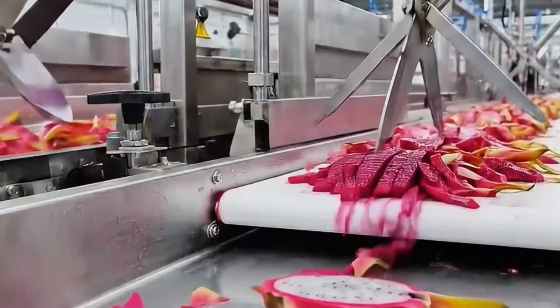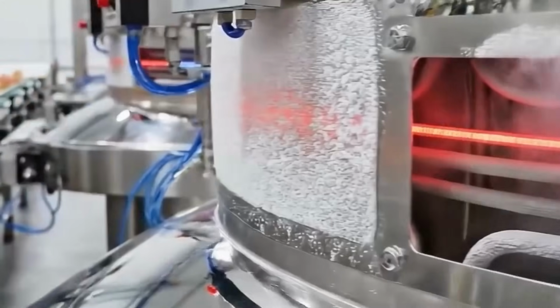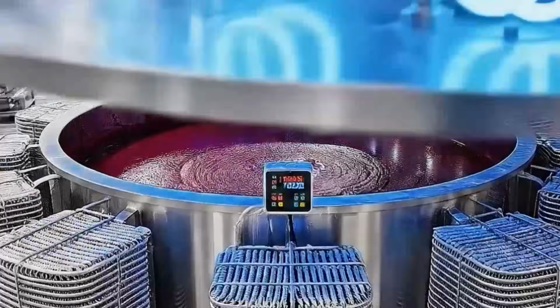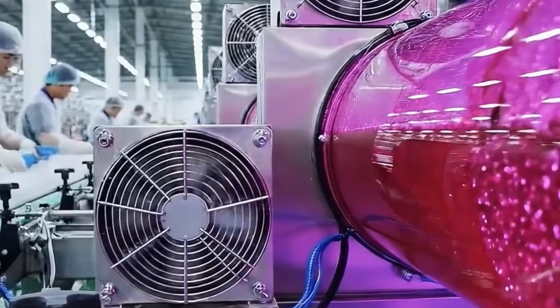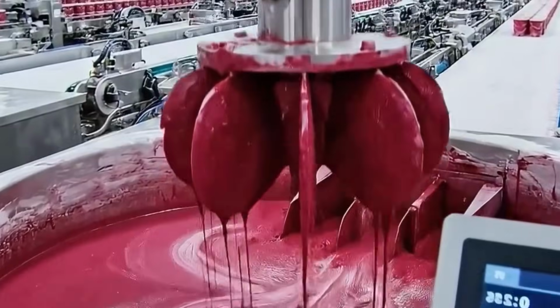Stabilizers and emulsifiers, including locust bean gum, guar gum, or pectin blends, are pre-dispersed into a slurry using a high shear induction system connected to a secondary mixing tank. The system uses a venturi-driven powder funnel that draws dry powders into a vortex of hot water, while shear blades break down clumps.